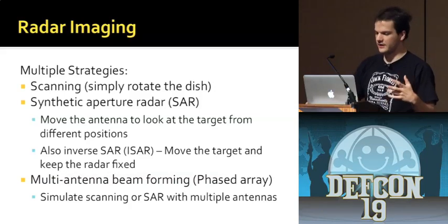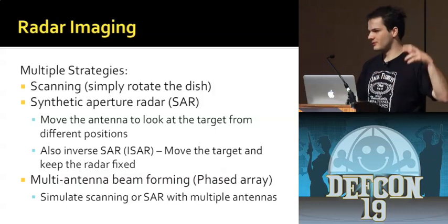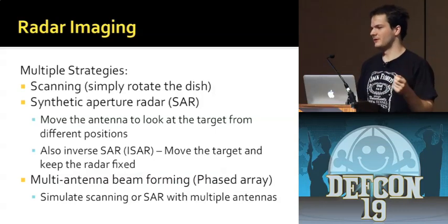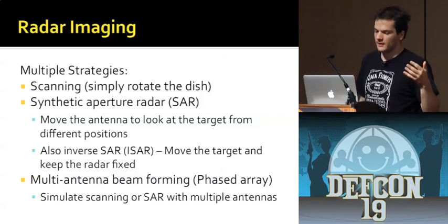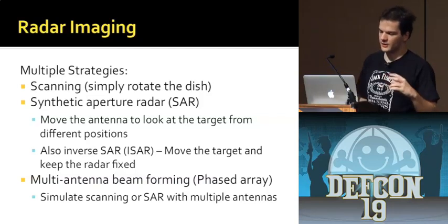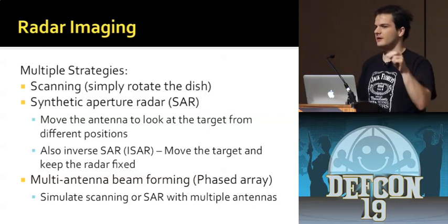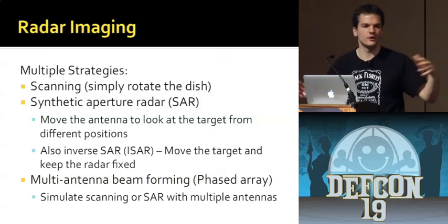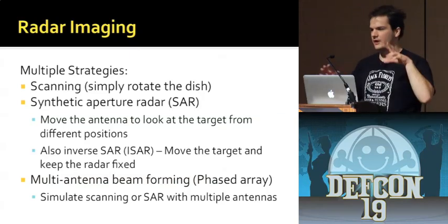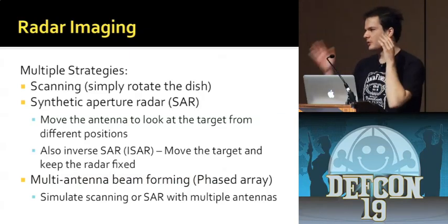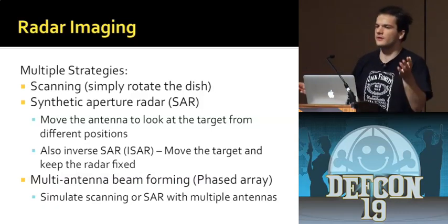There's something called synthetic aperture radar, which basically means you can get better resolution if you have a bigger dish. The problem is the bigger dishes are more directional, so that's the advantage. With synthetic aperture radar, you're taking coherent measurements of the signal at different places, and you're trying to simulate having a larger dish. The reason you would do that is so that you can get a finer resolution of space. If you just point it in one direction, I think the beam widths on these things are 40 degrees or something, so you couldn't see anything out there.